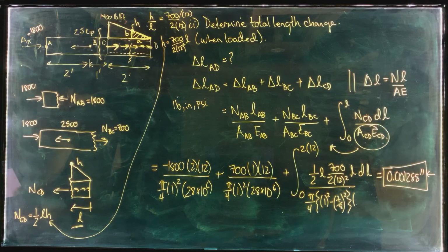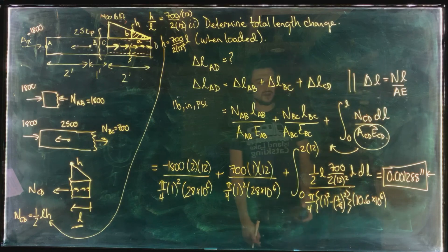And that's the modulus of elasticity for 2014 T6 aluminum. So if you flip to your material property table and locate 2014 T6 aluminum, it's right up near the top. Two grades of aluminum on that material property table, 6061 T6 and 2014 T6. It's 10.6 times 10 to the 3 KSI. So we've got 10.6 times 10 to the 6 PSI. Okay, thank you very much for pointing out that I had missed that. That's great.